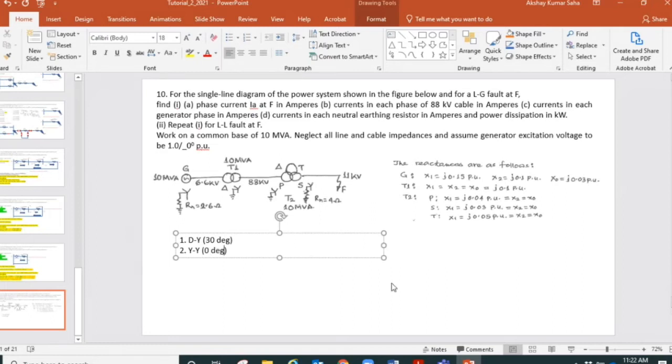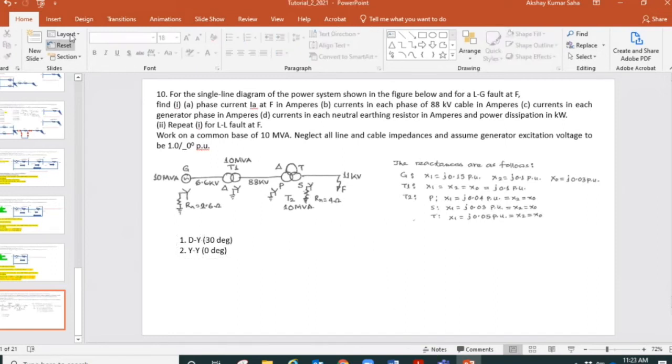So now I want to connect this secondary side, the Y side. Both the sides are Y, but there is a phase difference between these two voltages. Their magnitude is the same, their frequency is the same, but they have a phase difference of 30 degrees. Because of that, there will be a difference in magnitude of the instantaneous values, which we can always check from the sine waves. Do we have a sine wave here?